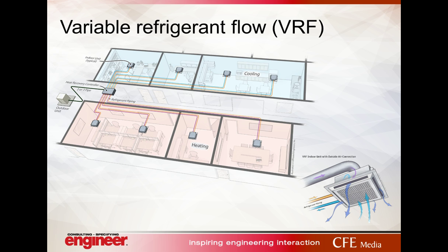Now, that applies to all occupancies, but the part that makes it particularly difficult for healthcare is that ASHRAE Standard 15 states that institutional occupancies have basically half the limit. So that leads you to having smaller refrigerant networks, meaning more outdoor units, and so it does cause issues.